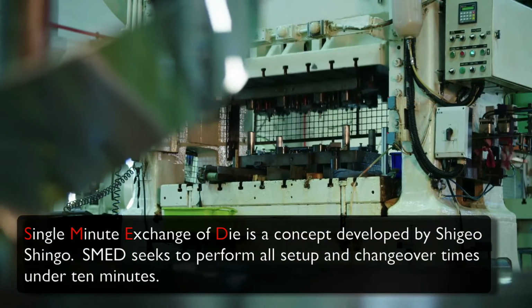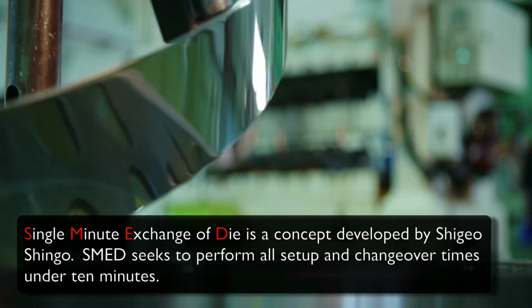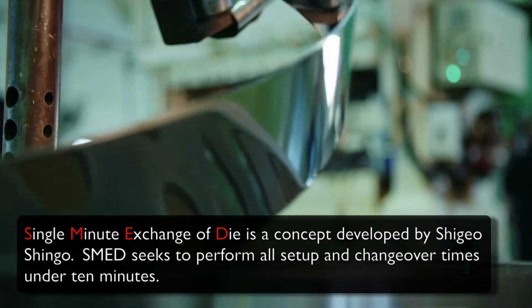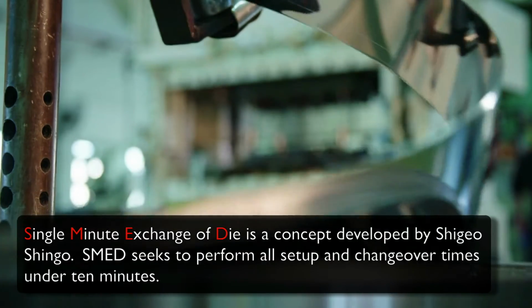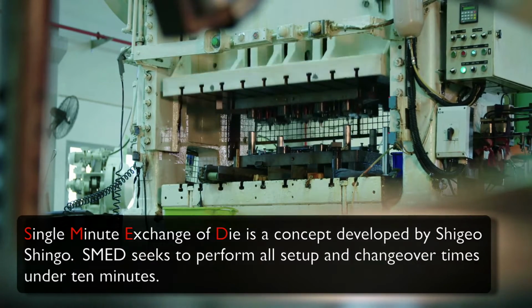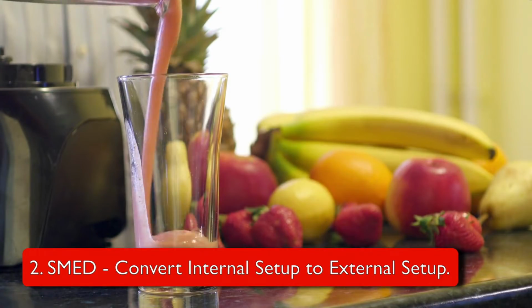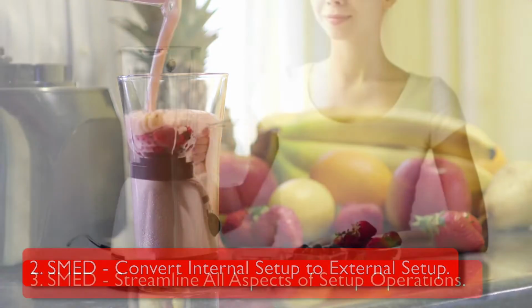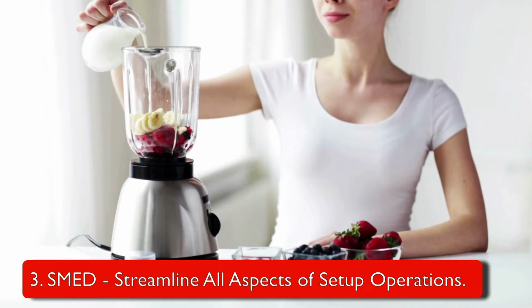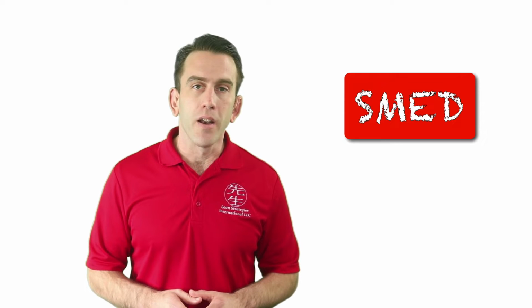Single-minute exchange of die is a concept developed by Shigeo Shingo. SMED seeks to perform all setup and changeover times in under 10 minutes. In other words, it seeks to complete all changeovers in 9 minutes or less. There are 3 main steps in the SMED system. Separate internal and external setup, convert internal setup to external setup, and streamline all aspects of setup operations. You will learn more about these steps later on in the course.